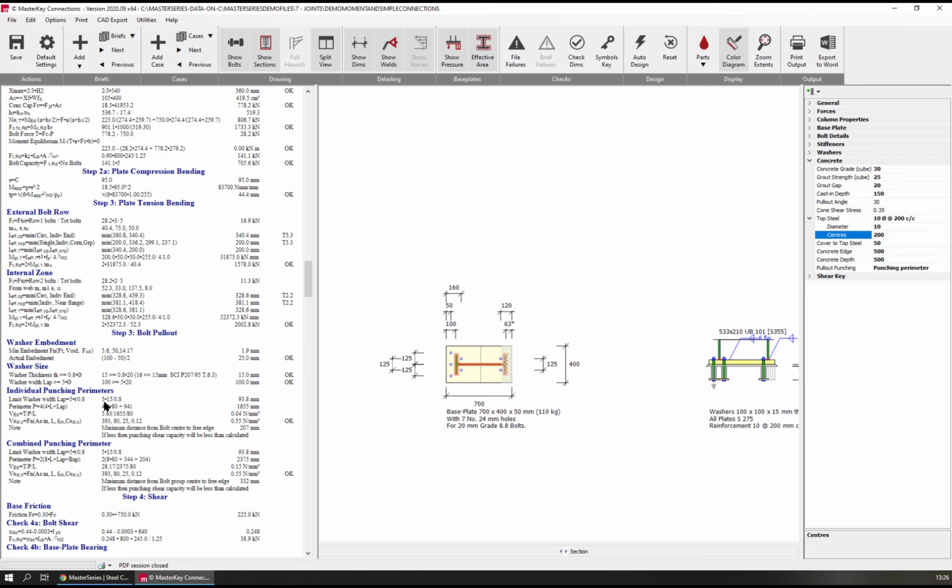And you can design all of the connections with multiple loading cases using this. And even for your foundations, for your base plates, when you look at your forces, you can even set up whether or not it's a fire case and use the altered load factors and stresses for fire loading, which is very interesting.